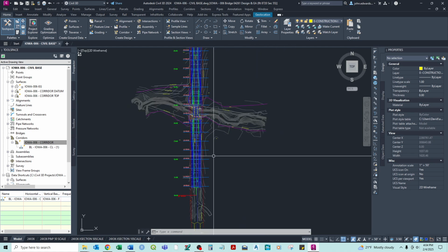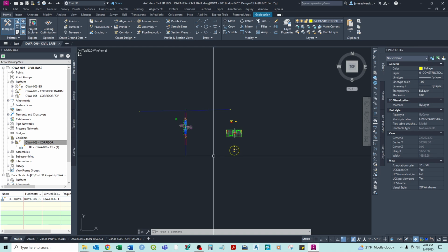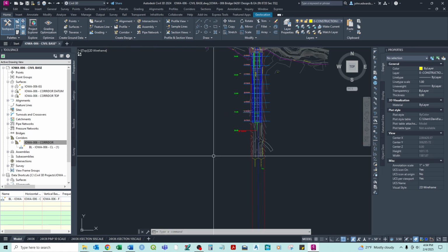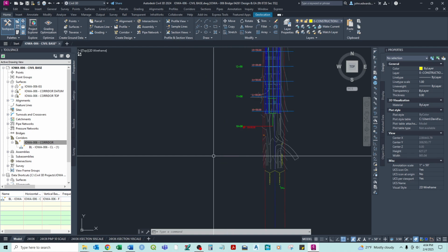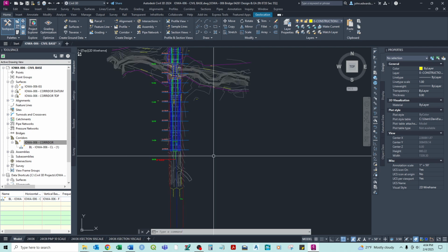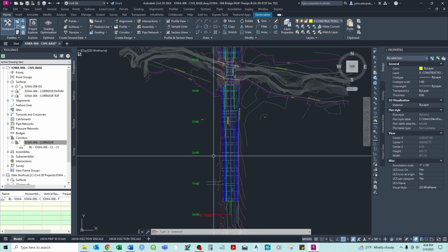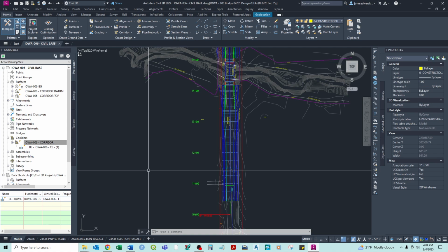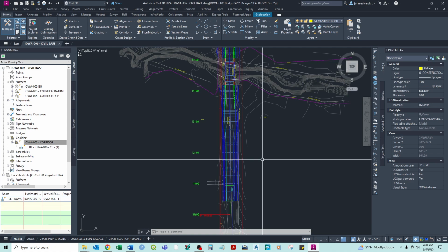So what I'm actually going to do is back up a bit, just hitting Control Z to undo. So now we have undone. One thing to note when you're undoing, every time you zoom in or pan around, that counts as a command.